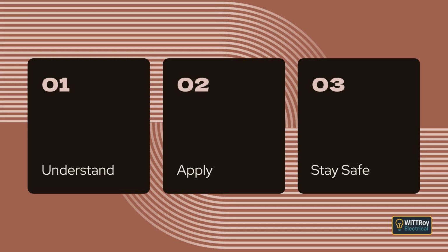Clause 2.3.5.4 Identification. This clause tells us how emergency devices must be marked. Any switch used for emergency stopping must be clearly marked or colored so that it can be identified straight away. Push buttons or handles should normally be colored red with a contrasting background. The goal is that anyone, even someone not familiar with the equipment, can immediately tell which switch will stop the danger. If a remote lanyard or chain is used, such as above a conveyor, it does not need to be colored red.